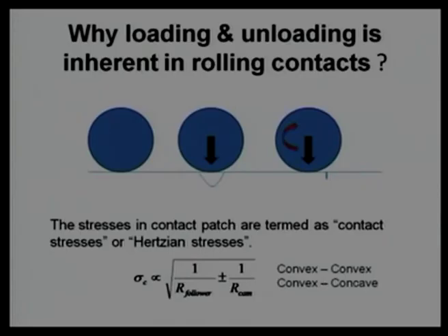Now, to find out whether really a dynamic load is inherent, this slide, this picture exemplifies that. It says that now load is applied and we know that the follower is going to rotate about its axis. It is slightly away, but because of the pressure profile, even if it is not coming very near to that, this surface will be experiencing some stresses.